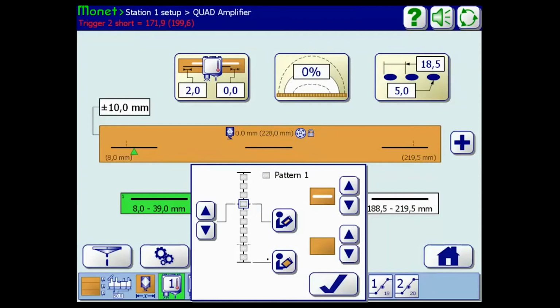Now, ideally, I think the background should be learned when everything is at temperature. So your valves are at temperature, your tank, your hose, everything is at running temperature, but there's nothing underneath the sensor. So basically, we're just learning the ambient temperature around that area, if that makes sense. I don't think there's any value in even having a carton or a product without glue underneath the sensor. What's important is that there is no glue under the sensor.